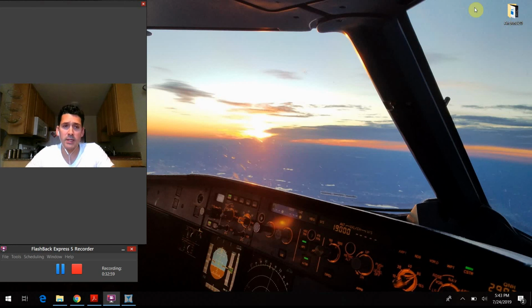This is a great question because the handling characteristics of the airplane are altered, of course, when you're taxiing on a single engine. So the steering itself actually doesn't feel that much different to when you're taxiing the plane around on 2 engines, but there are a couple things that are changed. The first one, being the obvious, is you physically have half of the normal thrust output that you would with 2 engines operating. So we do come into situations sometimes where there are some airports where you're taxiing up a gradient, if you will, on a taxiway, and you're physically needing to move uphill, and you don't have enough thrust in that one engine to get the aircraft moving all the way up the hill.